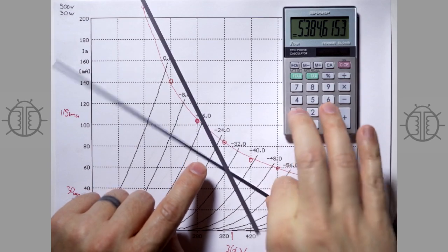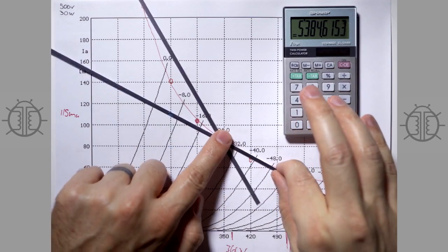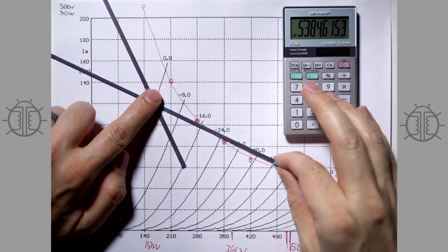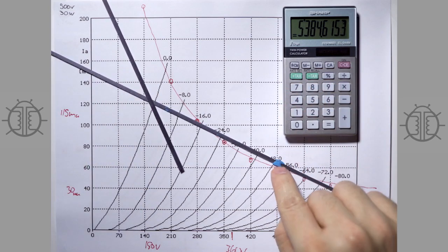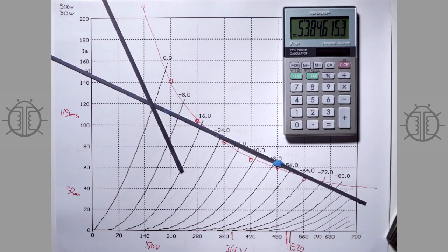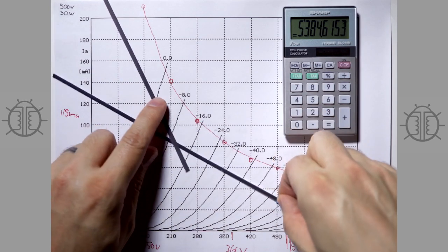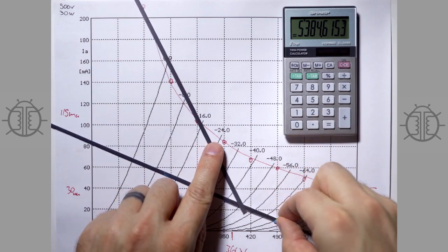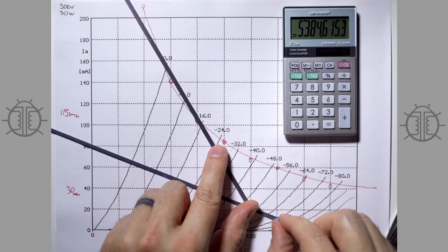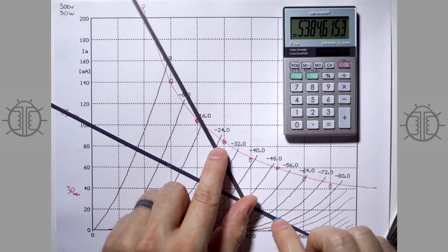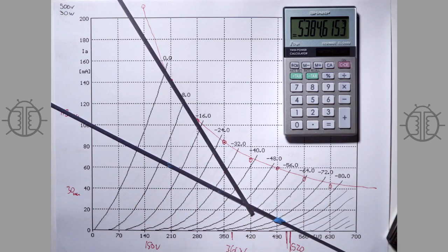So it would be like this. You move this all the way up. And once that gets up above 0 volts, that transition point, you never reach it. And now you've got a Class A stage again. And so you bring this down like this, and suddenly you're transitioning in Class AB much more quickly at that point. Hope that makes sense to you.